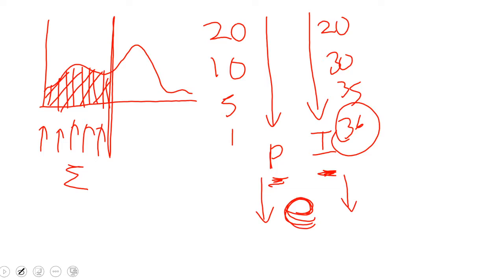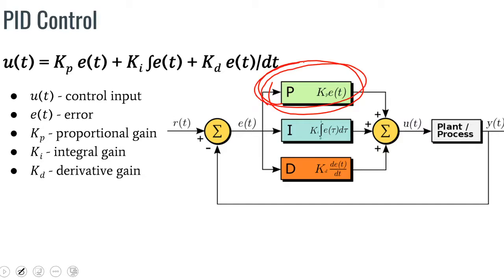So we can use the integration value towards the end, when we are closer to having less error. When the error is lower, the proportional component is almost insignificant, but the integration component will become the important one that is still going to control and stop the vehicle, or bring the speed of the vehicle as we expect.